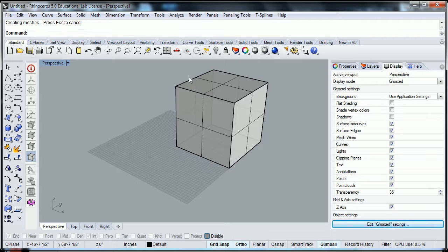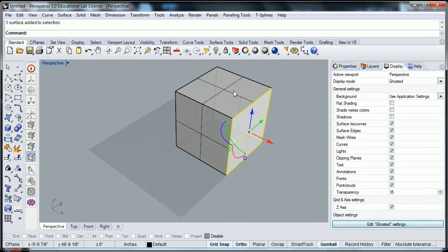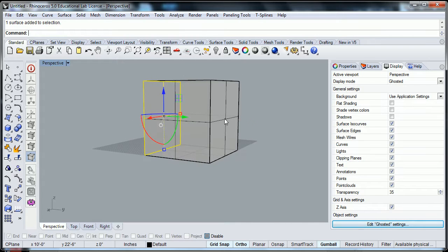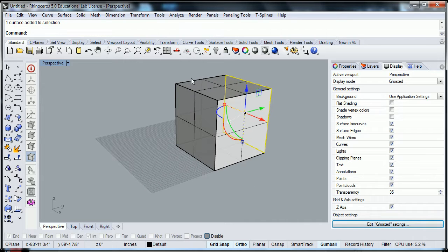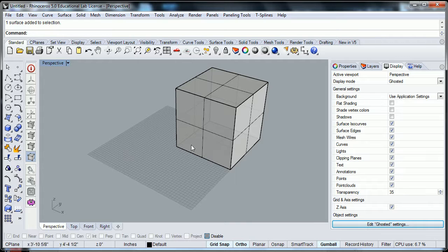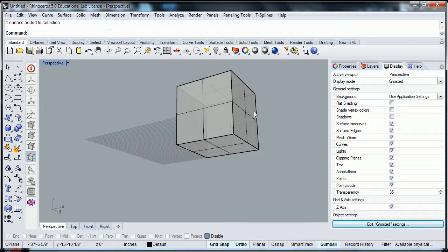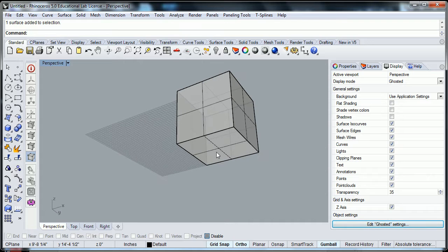What that does is it turned my object into a single plane, kind of like a paper box. Okay, now I can select each side at once. And if you have the gumball on, it should show the gumball. If you don't, it would just highlight the edges of your piece. Okay, but what that did again is basically took all those faceted pieces and made them all individual. Okay, and what we're going to do to replicate this box is that we're going to take this bottom out.